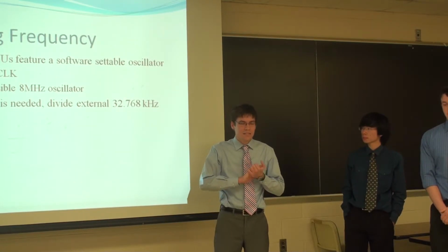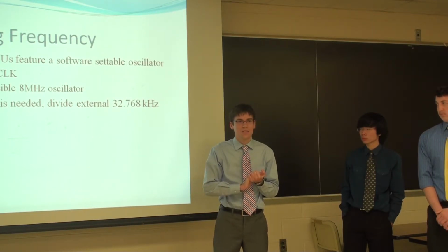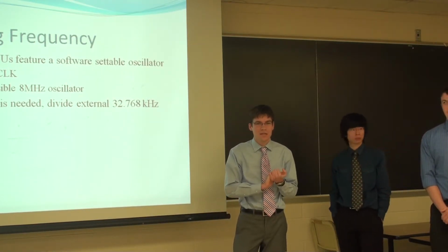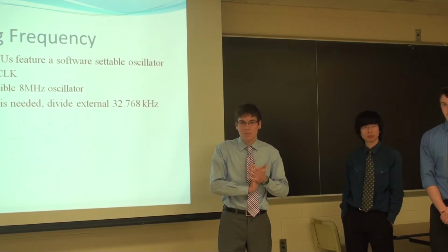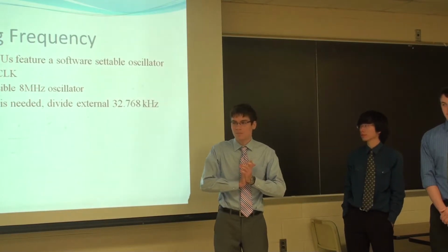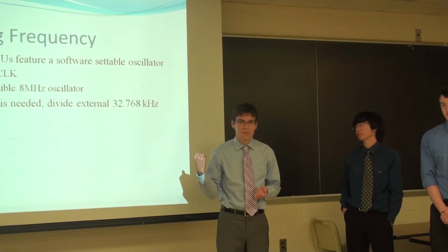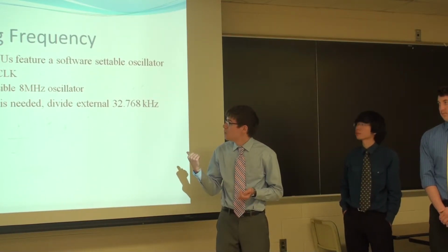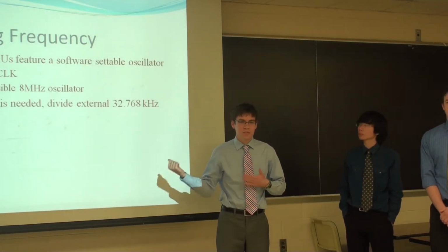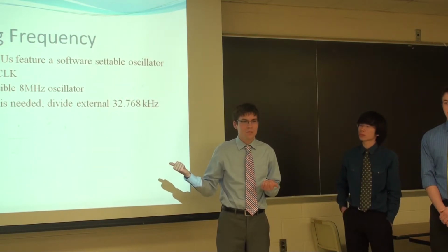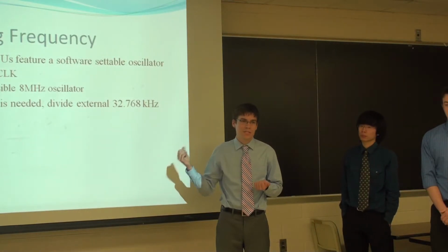Now there are downsides to these internal oscillators, and the main downside really is that the speed of the oscillator tends to vary highly with changes in supply voltage and in device temperature. And so when you need accurate time, like we do to run a real-time clock for our project, you'll often have to use an external quartz clock oscillator. The problem there is that while you do have a more accurate clock, generally in that application you can't turn it off that much because then you lose your clock signal. What you can do is sleep between